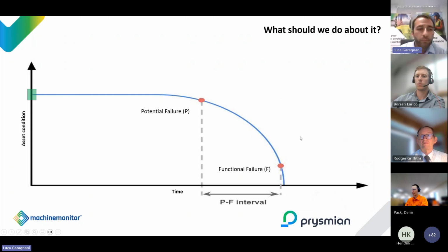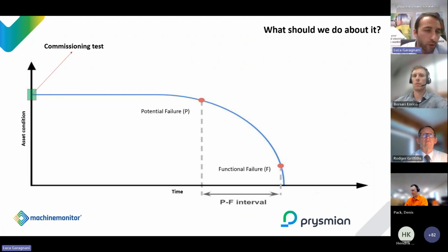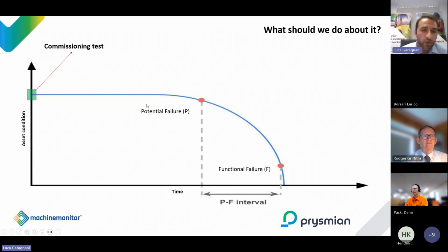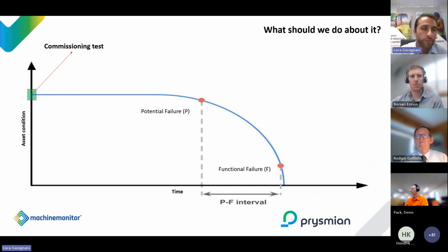But we can focus on what we know, right? If we do proper commissioning, that is when we do the test, we try to have exactly this graph. So if we do proper commissioning, we make sure that the asset has no existing defect. This is slightly different for machines, but let's talk about assets that don't normally have discharges, like cable, transformer, and switchgear.